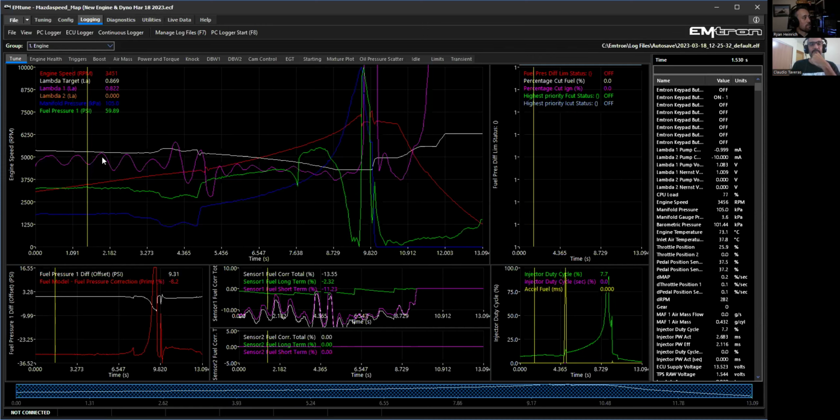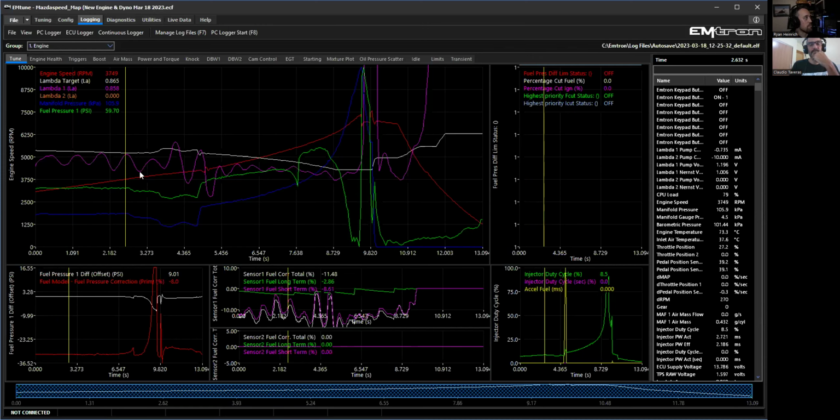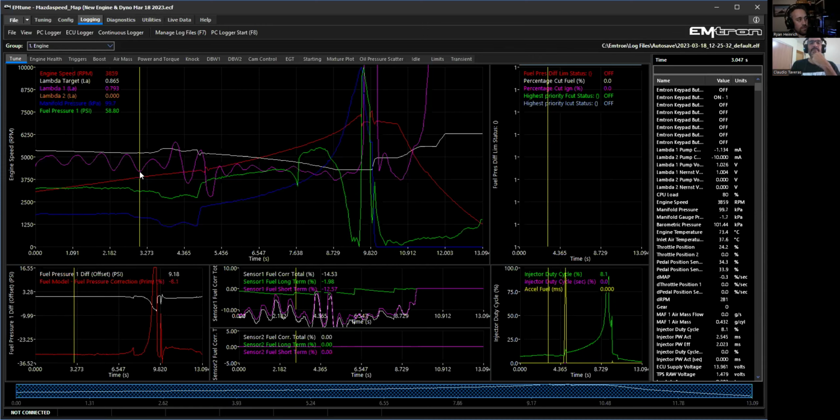What's probably happening here? Do we see differential pressure? It's an 8% change down on the left side. So what's very likely happening is I don't think this is a fuel dampening issue as far as on the rail with a fuel pressure damper. This is most likely as simple as the PID control for the Lambda controller is a little bit too aggressive. That's most likely possible, yeah, it is possible for sure.